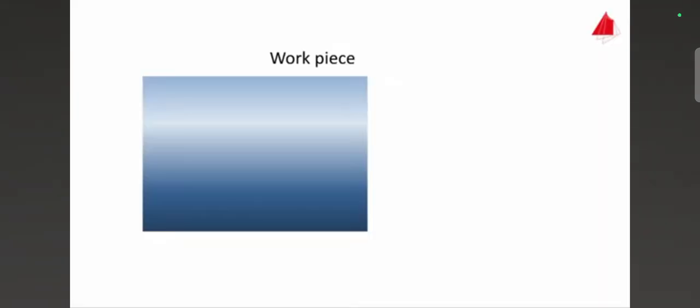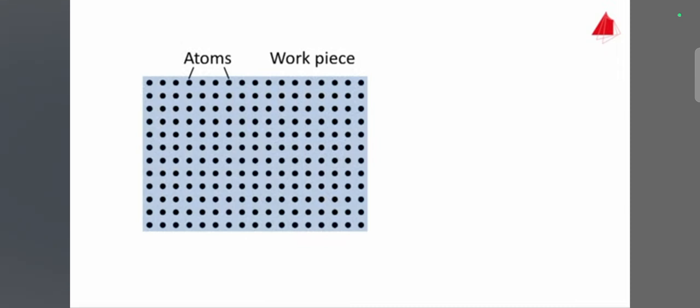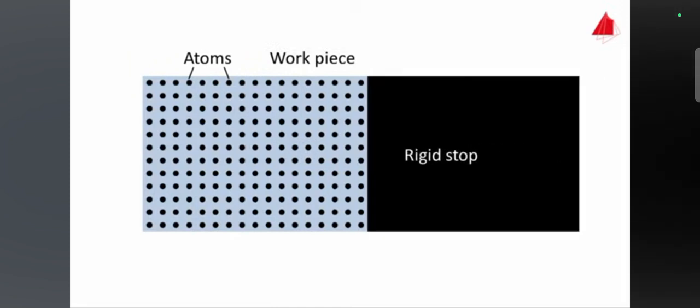examination. The basic principle of ultrasonic testing of materials is the propagation and reflection of sound waves. As an example, a cylindrical workpiece is shown in the animation. The longitudinal section through the cylinder shows the position of the atoms, extremely magnified and simplified as a single crystal. To begin with, a rigid, unyielding stop is attached to the right front end of the cylinder.